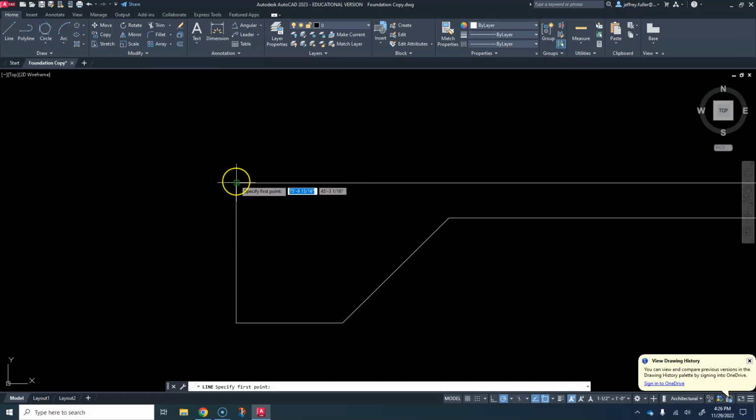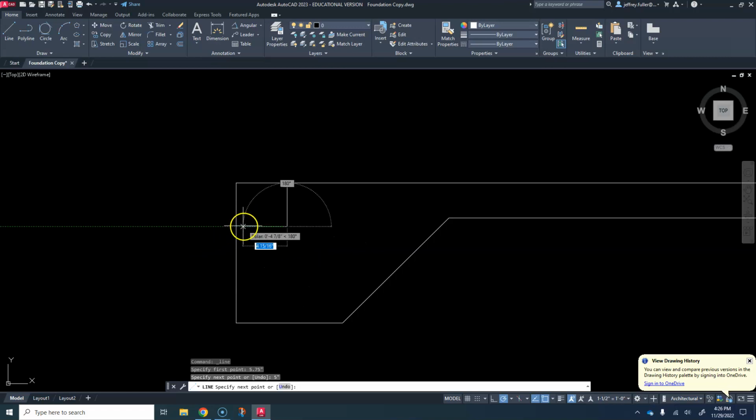I'm just going to hover and activate that point of geometry and pull my cursor to the right, and you can see that dashed green line following it there. And what that means is I can type in 5.75 inches, enter, and that line basically starts drawing at 5.75 inches, or 5 3/4 inches, from that corner. Okay, I'm going to draw it down just 5 inches. It might be a little bit of overkill, but oh well.